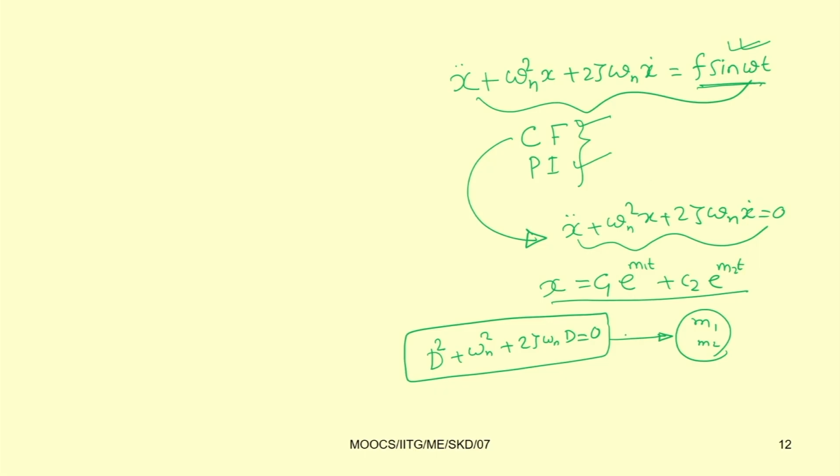and you can get the complete solution. But you can see, as t tends to infinity, particularly in the case of mechanically vibrating systems, if there is damping, this complementary part always tends to 0 or dies down. As the complementary part dies down, you will get the steady state solution, or the particular integral part of the solution. That thing we will see at a later time, but in today's class